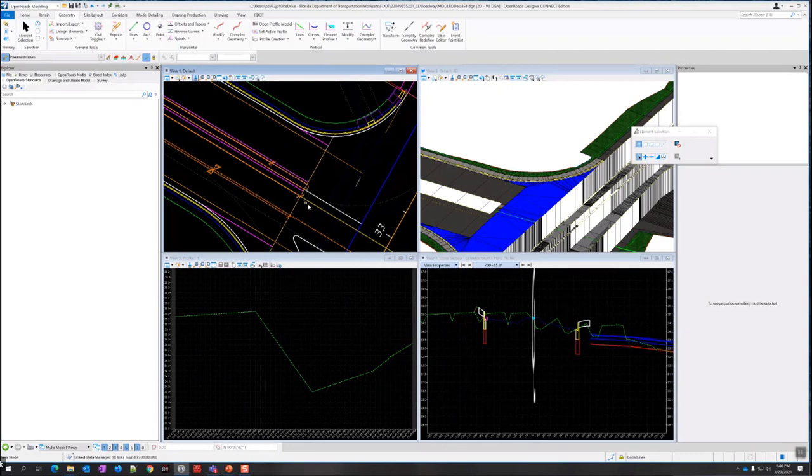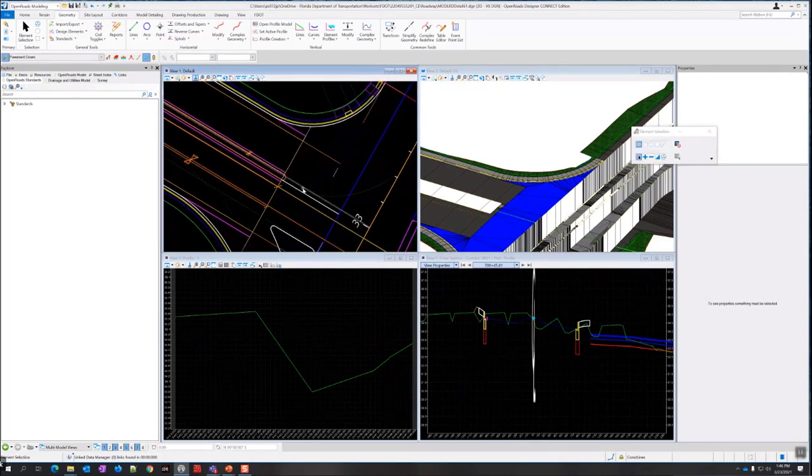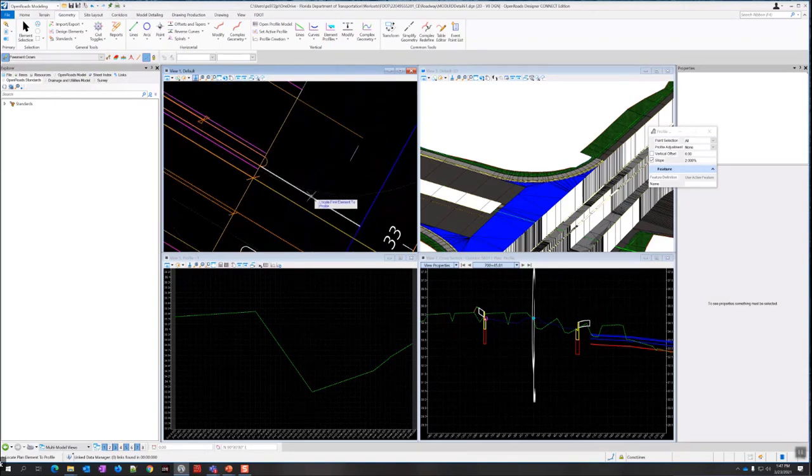Okay, so we're getting ready to go into the project this slope over. So I'm going to go to the element profiles, click the drop down on that, and then we're in geometry in the vertical section. And I choose profile by slope from element. First element to profile, that's going to be this line that we just created.